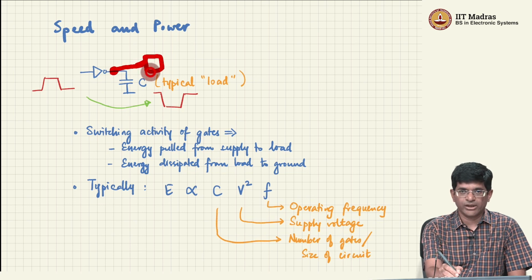But from an electrical point of view, I don't really care what that logic is. What matters is that it looks to me like a capacitance, right. And what that means is I can either have a 0 voltage on this capacitance, meaning that there is no charge stored in the capacitance and there is no current flowing through it, or this voltage over here goes high to VDD. I still have no current flowing through this, because that is how the gates are constructed, right. I don't have a static current flowing through this. So unless there is a very minor form of leakage current, as a first approximation, I can basically assume that there is no current and therefore this is just a capacitance.